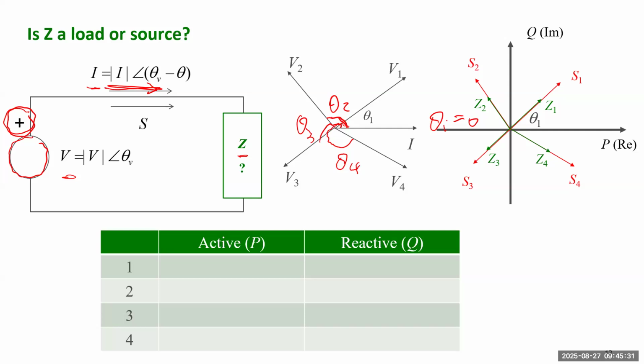You either calculate the complex power, then put it in the 4 quadrants to see which quadrant it really falls into. If it falls into the 4th quadrant, it will have negative P and negative Q. You can also decide to calculate the impedance, and because impedance will be parallel with the complex power on the complex plane, either one, whichever is convenient to you.